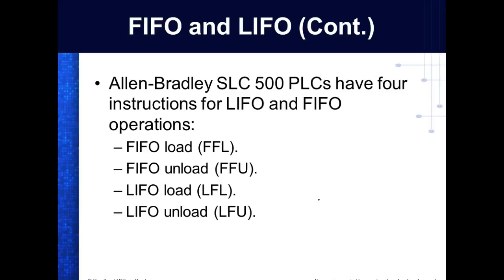So here are our four instructions. FFL, this would be a what? This would be a push. FFU, this would be a what? Pull from a FIFO, okay? LFL would be what? Push on a LIFO, and LFU would be what? Pull or pop. Everybody okay? So load means push and unload means pull.